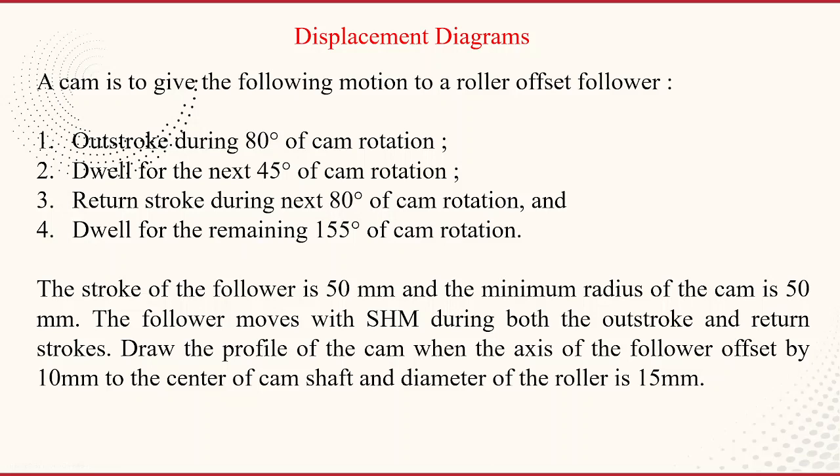Draw the profile of the cam when the axis of the follower is offset by 10 mm to the center of the camshaft and the diameter of the roller is 15 mm.